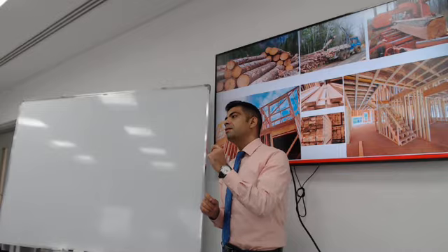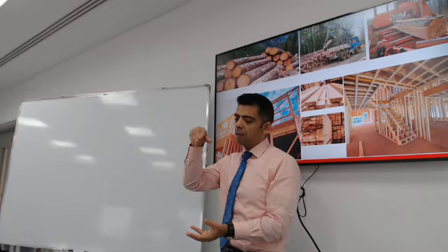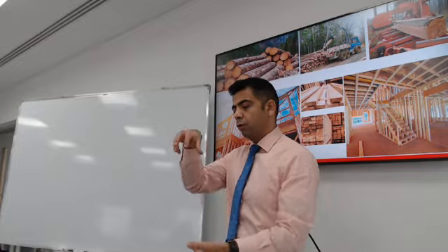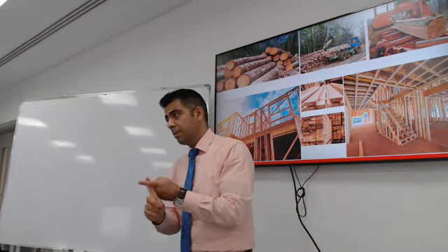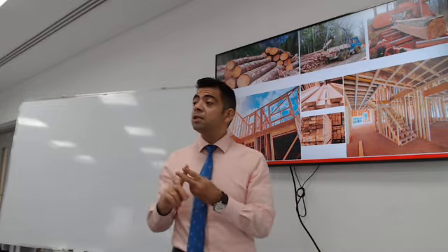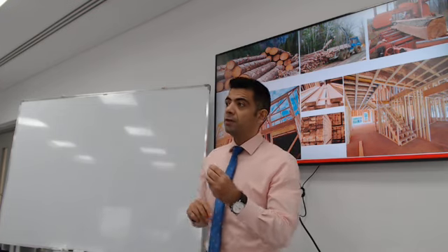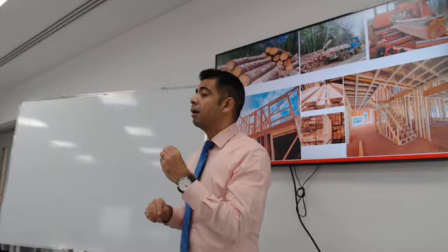There is also another important aspect, which is the load direction on the fibers of wood. If you're loading the wood section parallel to the grain, its capacity is different if you rotate it 90 degrees and apply load perpendicular to the grain of wood. So the direction of load matters. The species of wood matters. Also, the grading of wood.